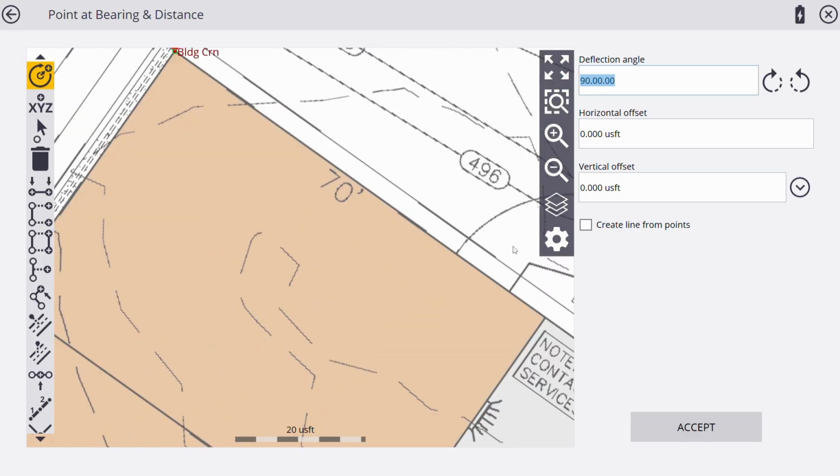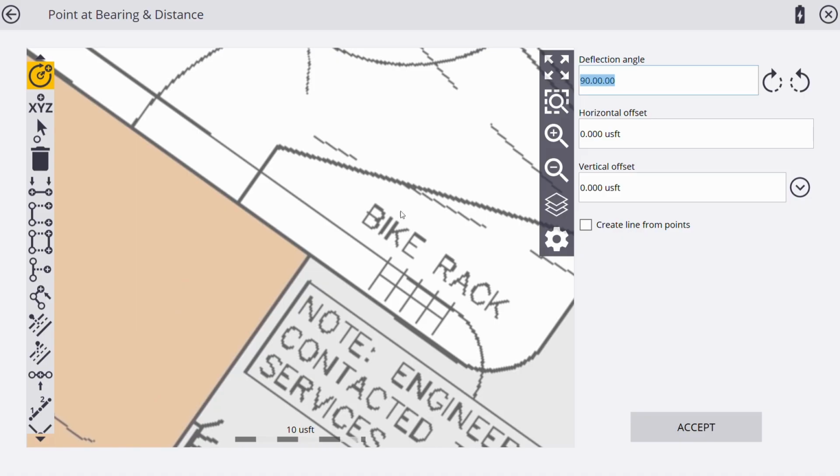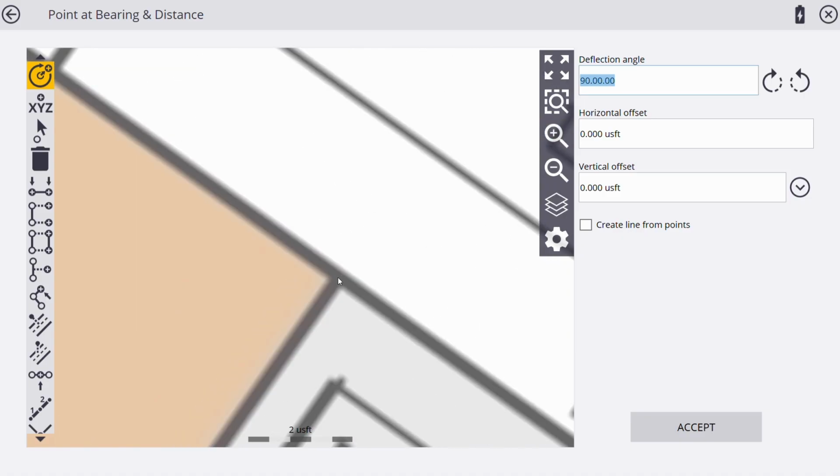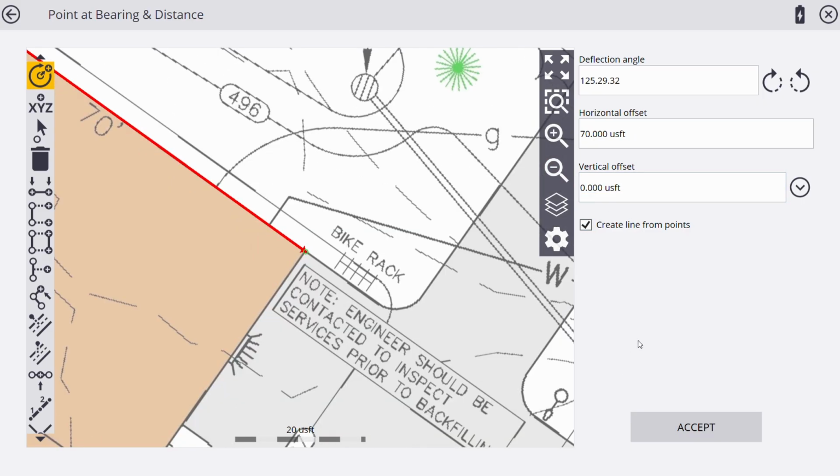Now if you've watched our other videos, you know we like to bang 90s around the building. So I'm going to come over here and get my bearing. I'm going to choose right on this. So 69 feet, we know that's supposed to be 70. We're just going to push it. What's nice is now I can click on create line from points, 70 feet. We're going to hit accept.